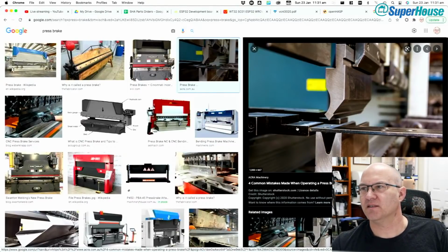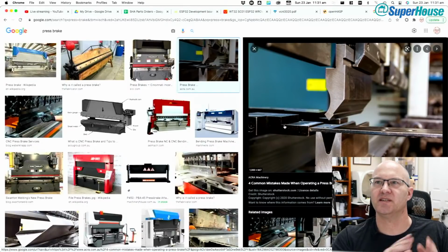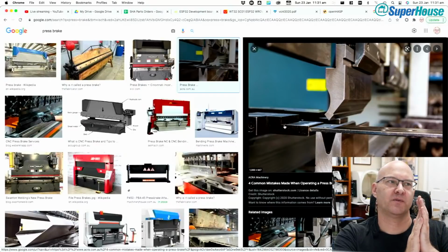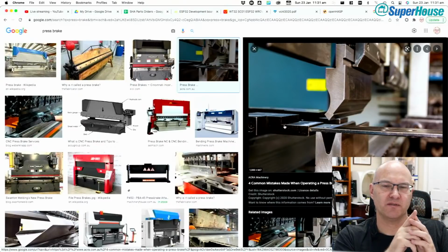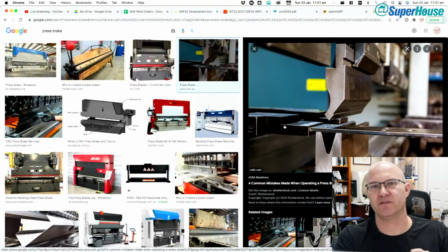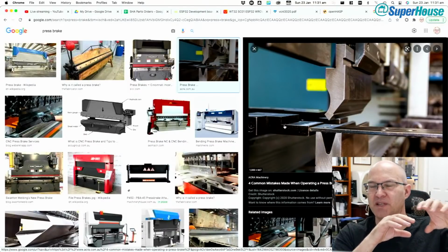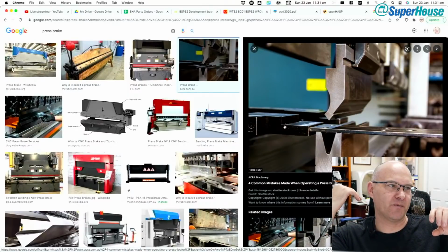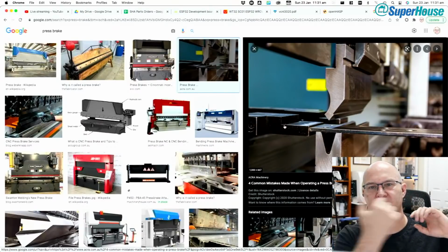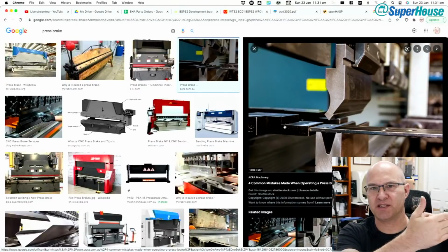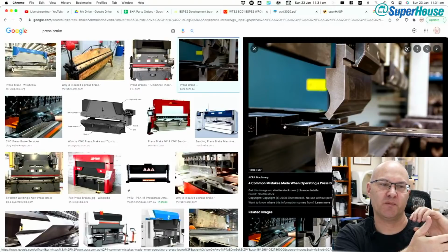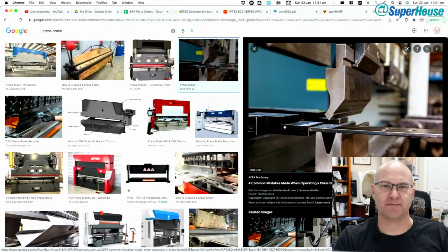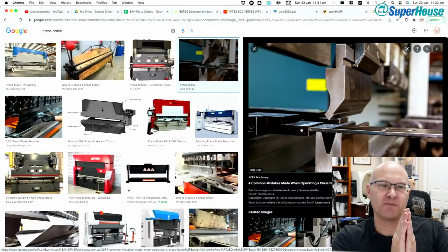And he wanted a way to be able to control the position of that. So what he wants is three things. He wants a stepper motor control, which can then go to something like a ball screw. So there'll be a ball screw that will move that back piece into the correct location. It could be closed loop, but to keep it simple, what we'll probably do is just have a limit sensor, like a homing sensor. So we need a homing switch input, and we need a brake, because in order to make this really lock into place, there will be a brake.